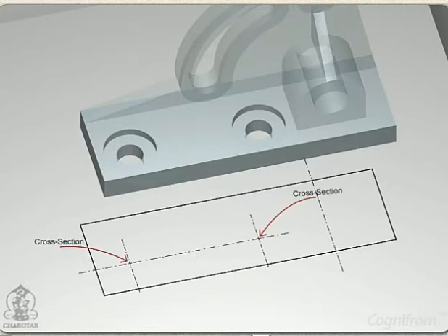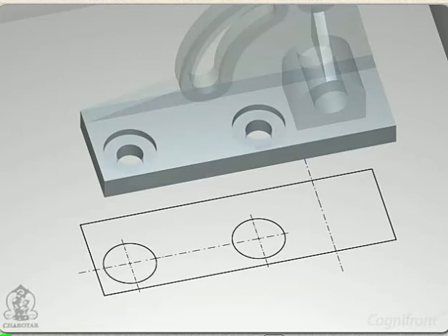Note the intersection points of this line with vertical center lines. Using these intersection points, draw 2 spot face holes with a 30 mm diameter outside circle and a 15 mm diameter inside circle.